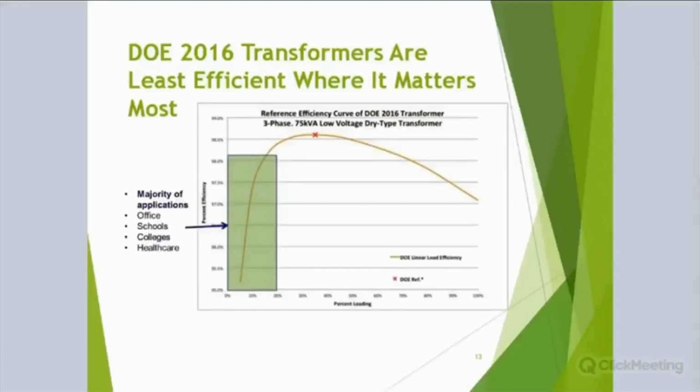You can have some specific applications where you know what the loads are going to be, and they become much higher loaded transformers, which is good for trying to get closer to that peak of 35% loading. But as you notice, the efficiency of a transformer also drops off as you get higher loaded, a highly loaded transformer, unless you build a transformer for that specific application, which a few manufacturers do, most don't.